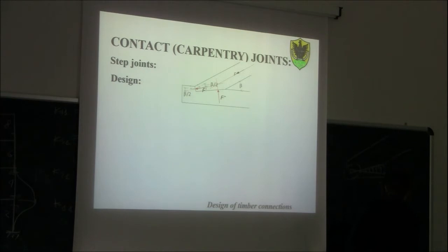Like this. So if this one is outside, theoretically your neutral axis should be here. So theoretically you should have something like this. But we said this one is not permissible because unless you put a pile here, otherwise the soil cannot take down the footing, because it's not glued to the base of the footing.